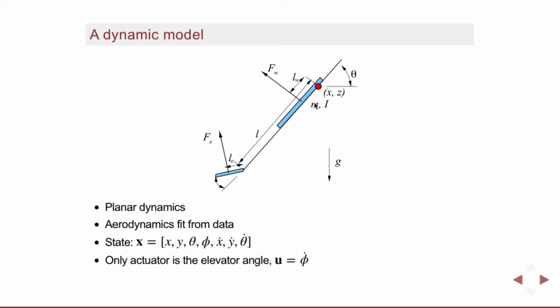Okay, so we have an XY position of the plane here. We've got aerodynamic forces coming from the wing. For a flat plate, it's at the mean aerodynamic chord, even though most other airfoils would operate from the quarter chord. This one's from the mean aerodynamic chord. We have an aerodynamic force. Same thing, we're going to model the elevator as a second flat plate. Okay, we've got a pitch we care about, x, z. We have an angle of the elevator. That's our state space.